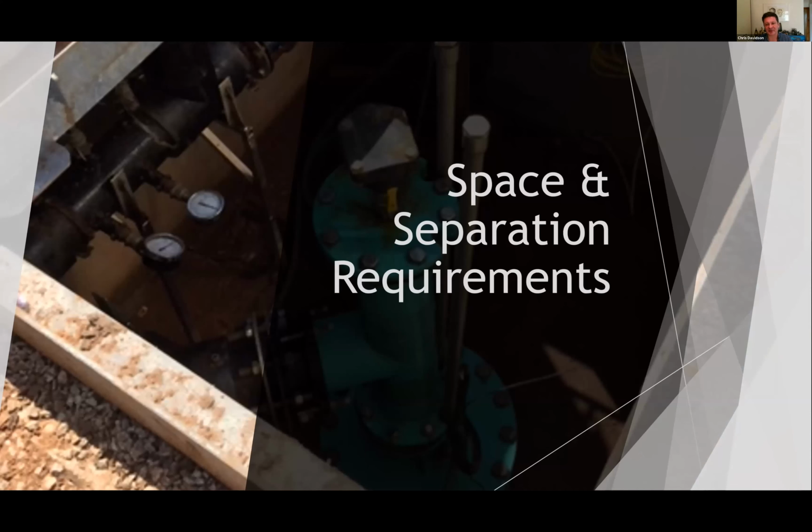So final couple of bits, space and separation requirements. The space required between boreholes is one of the most difficult subjects to deal with. And the next presentation in the series will be all about how we model that in a lot of detail. The rule of thumb is 100 metres is adequate separation between wells that take water from the ground and wells that put water back into the ground.